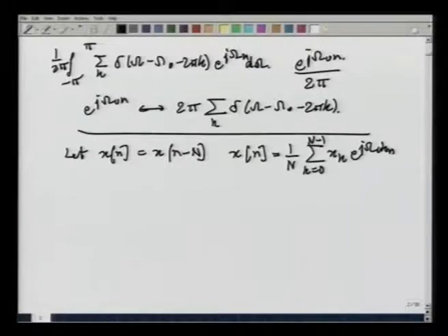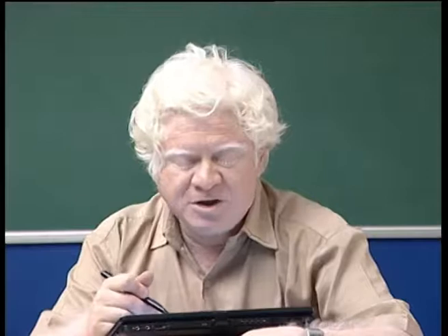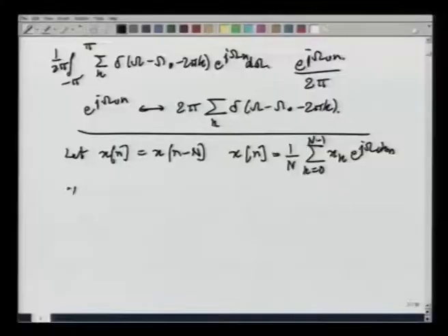Now, what do we get? This is a sum of exponentials weighted by the respective X[k]'s. Can we try to find the DTFT of this sequence? This can definitely be done, because all we have to do is to treat each term in this expression in the same manner that we have handled a complex periodic exponential in the previous example. So, we will finally get